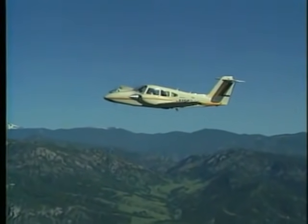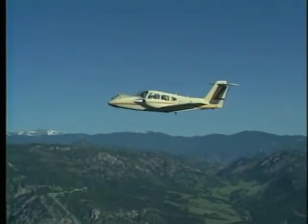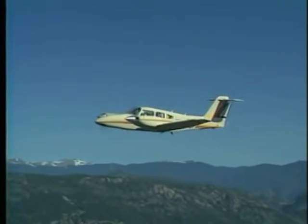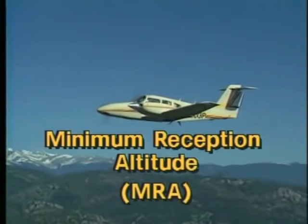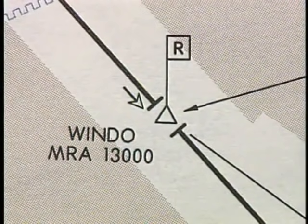At some intersections or fixes, terrain can interfere with the reception of the nav aid, which forms the fix. Where an altitude higher than the MEA is required to identify the fix, a minimum reception altitude, or MRA, is designated. A flag with an R is attached to the fix to indicate an MRA. The altitude is listed near the name of the intersection. In this case, you must be at 13,000 feet in order to identify Window intersection.